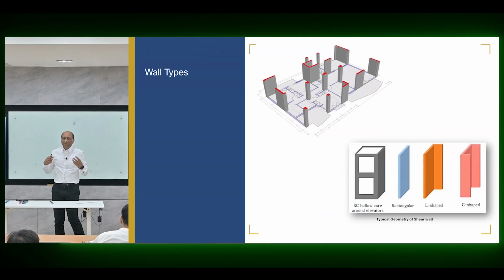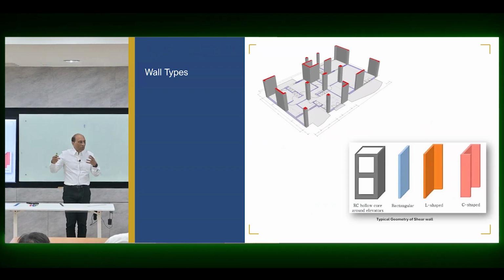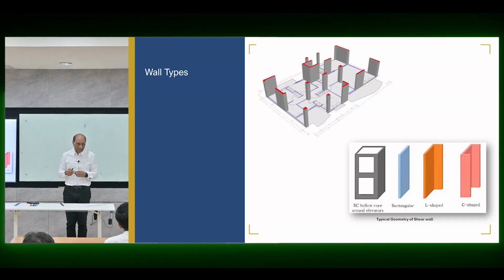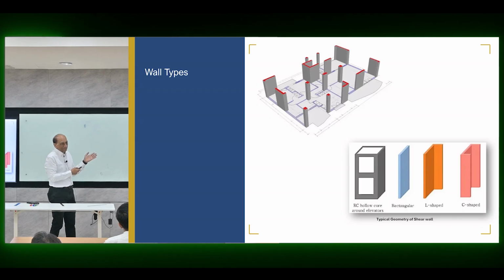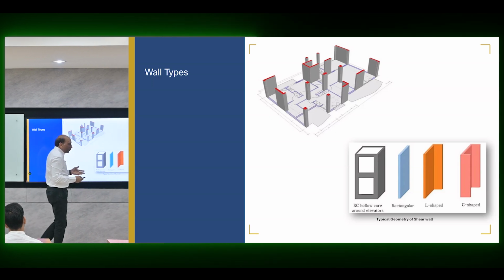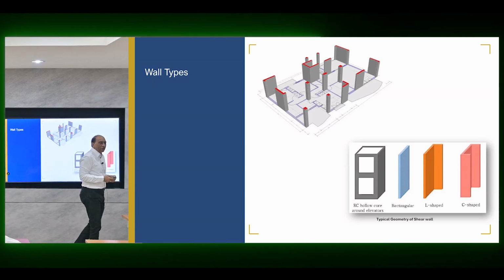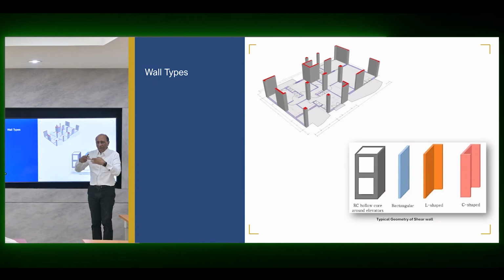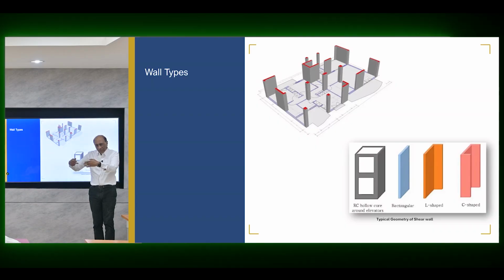Now the trick will be to utilize all these things effectively, connect them together as much as you can, finding where the best connection will help us. Okay? Because architects will not really want something like that. So you have to start with what is available and try to figure out what I can connect, where I cannot connect, what kind of effect I will utilize. Start with frame-shear wall interaction, to frame wall coupling, to wall coupling, right? These three things you already know now.